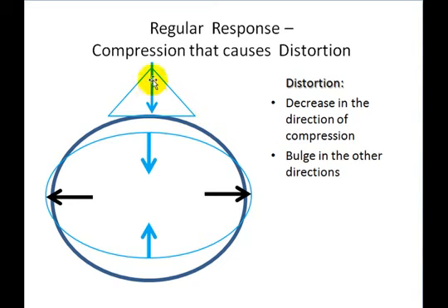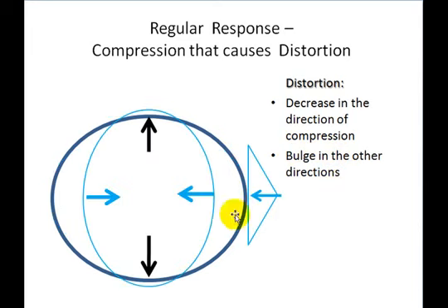What happens, you see, if the loading comes, for instance, from top to bottom, the object of impact, in that sense, would be signifying the image of the cross-section of the body, it gets narrower, the height decreases in the direction of loading, and there is the bulge that takes place in the other directions. So if the direction of loading changes, so does the response.